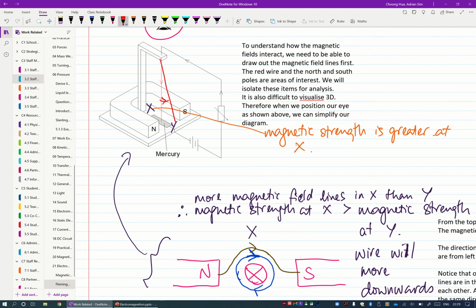And the amazing part is that when it swings in that direction, it gets disconnected from the electric circuit, because remember I said the lower end is resting in mercury. It's not really connected or locked down, it's resting in the mercury. So when it swings away from the magnet, the circuit gets disconnected and current stops flowing, and then it swings back in.